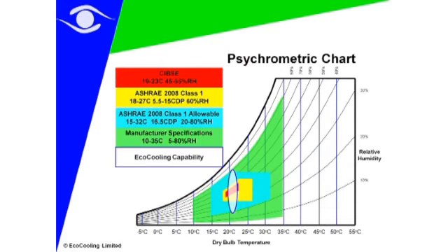Let's look at this on the psychrometric chart. The psychrometric chart is the tool that engineers use to understand the relationship between air and water. There is temperature across the bottom, the horizontal axis, and specific humidity vertically. The hotter air gets, the more water it can support.